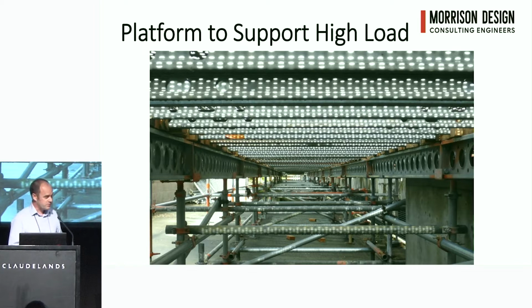So what we've done through here is we've installed timber blocks between the scaffold deck and those soldier beams which are running in and out of this photo. And that transfers the load directly from the top of the deck. The deck doesn't really experience the force. Load goes directly into these soldier beams. As I mentioned, the exact location of the equipment is fairly important here. If it started to drift off to the left or drift off to the right, it could be fairly catastrophic and fairly expensive mistake.